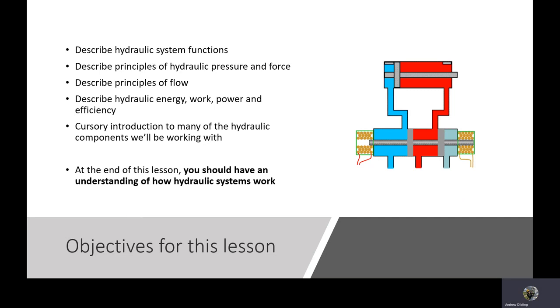Now, some of the applications of hydraulics would be in presses, where you need large amounts of power, automated material handling equipment. Many warehouses now are automatically, robotically controlled, and they use hydraulic circuits to move pallets and stack them in the racking. Tubing benders, robotics use hydraulics quite a bit, and actuators to control large valves and drives for conveyors for all kinds of applications.